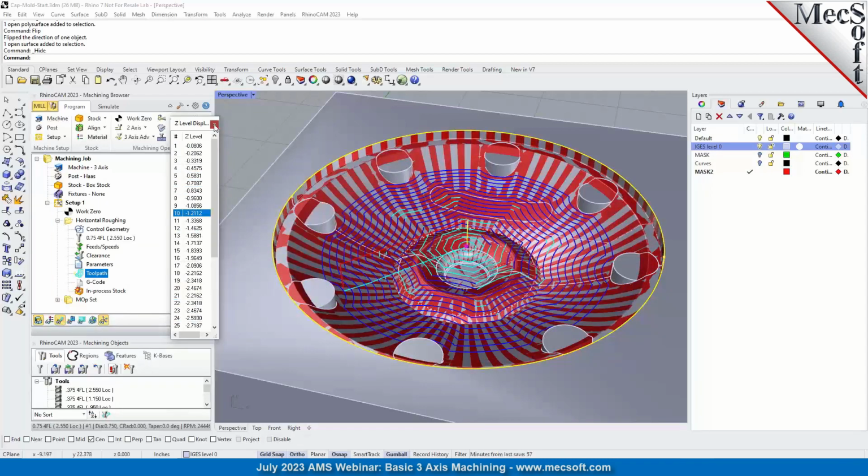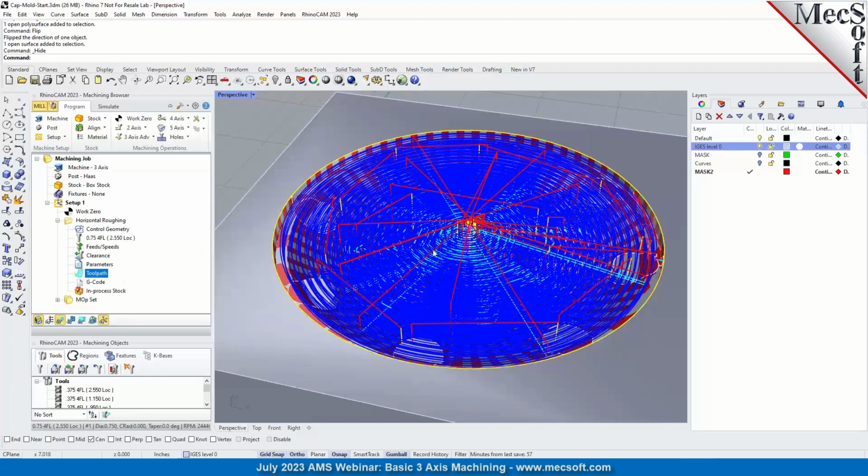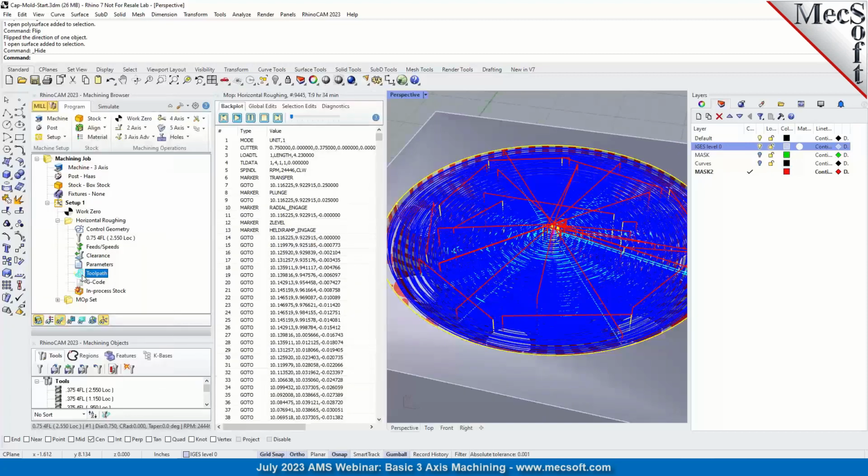Okay. And then another good thing to do, you can double left click on the toolpath icon, and it'll display the toolpath viewer / editor. If you're in the standard configuration or below, express or standard, you'll only see the tool motions. You won't have any of these tabs up here.